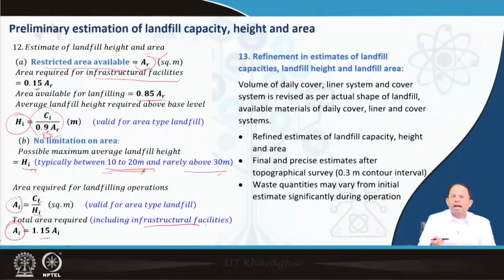Now, as you understand, this is the preliminary estimation of the landfill capacity, and that also a very, very crude estimation. I will show you some examples later. But if I need to do the actual, we need to refine these estimates of the landfill capacities using the actual landfill height for that particular area, considering the local context. So the volume of daily cover, liner system and cover system is revised as per the actual shape of the landfill.